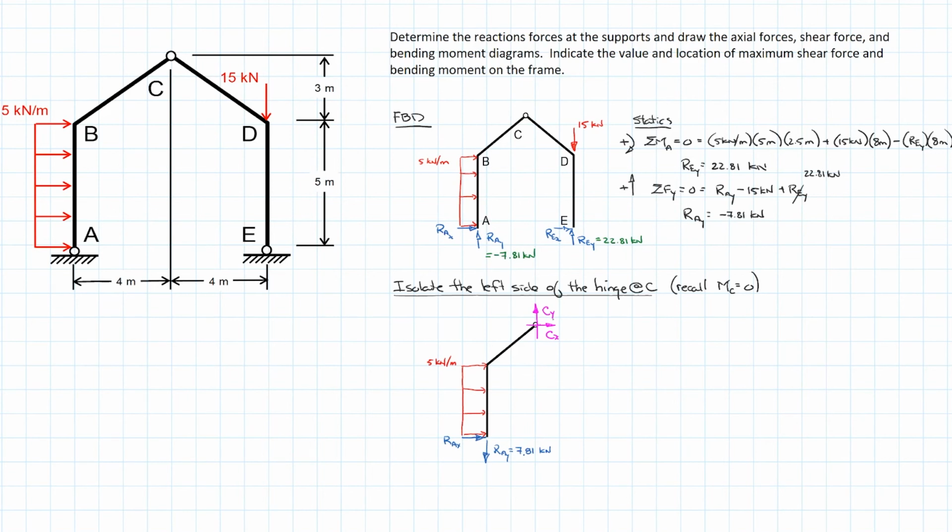And note that I choose to draw those in the global coordinate system. The global coordinate system may as well indicate here. We've assumed it, but we'll do X and Y. And wherever possible, I'm going to stay in that global coordinate system because it's going to simplify my process. And I'm only going to deviate from it when I have to later to draw the shear force and bending moment diagrams. So with this drawn out, we actually do have what we need to resolve the next thing.